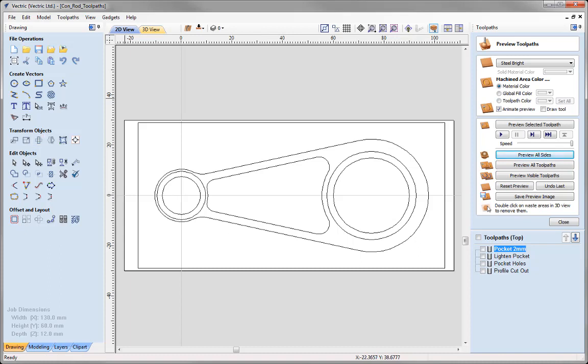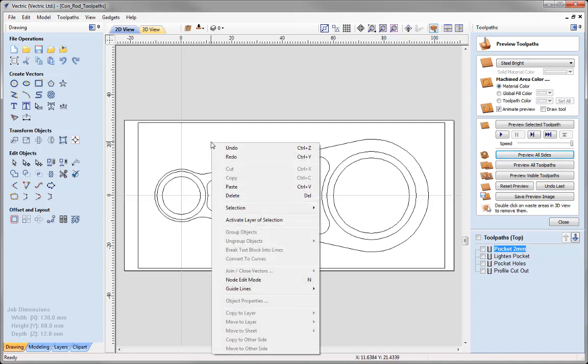A way to access certain functions in the software is through context-sensitive menus, accessed through the right mouse key. And this varies depending on the state of the part and what you have selected at a particular time. Now, if we just right-click in the white space, you'll see I'm presented with a variety of choices. Context-sensitive means that we get a menu appropriate to a particular part we may have clicked.